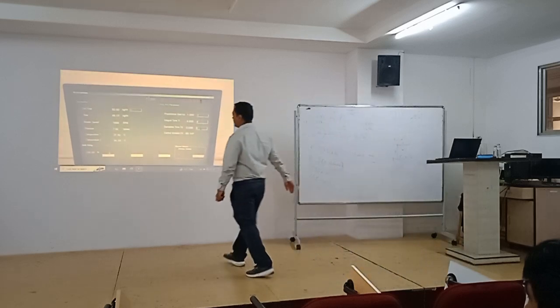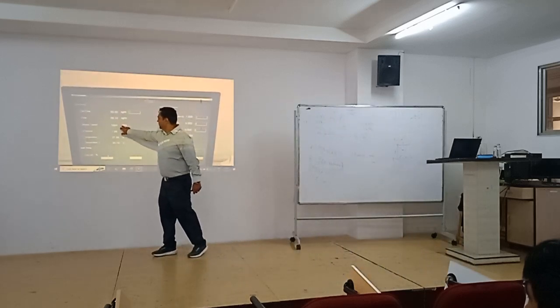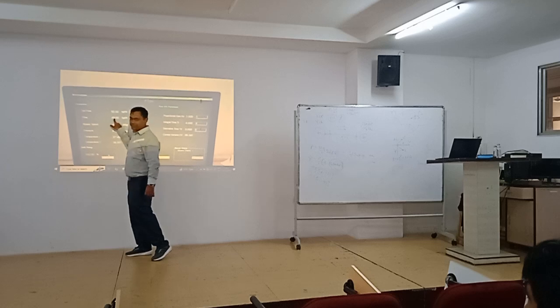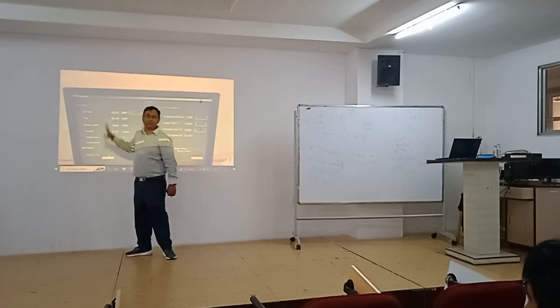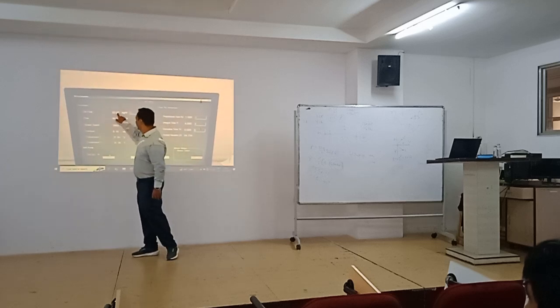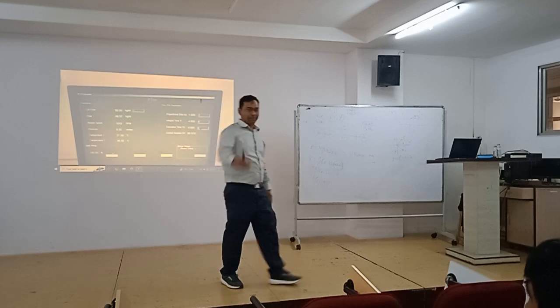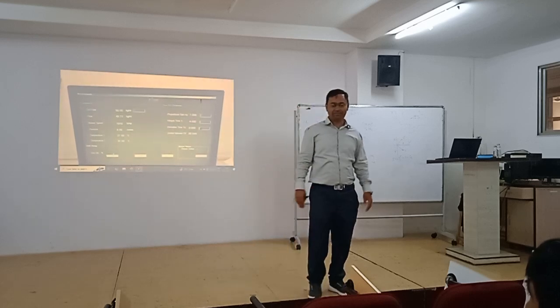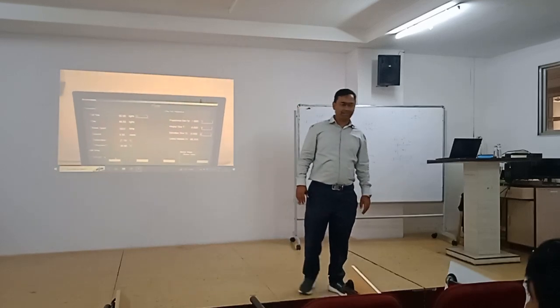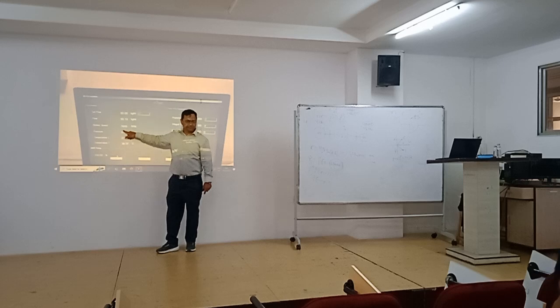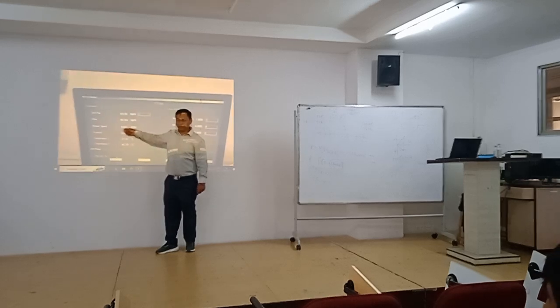See, what we can see here, number one, speed is increasing. There is not much variation in the actual flow. Desired flow is 50, actual flow is varying, but that effect is nullified. See, the problem is there, but more or less it's nullified. And that is nullified because your blower speed is increasing.